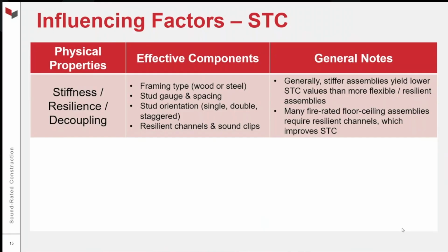So thinking about those effective components, the framing type, whether you're talking about wood or steel, is going to be a factor. Stud gauge, stud spacing, that's very, very important. Stud orientation: do you have a single stud wall, a double stud wall, a staggered stud wall? Are you using decoupling elements like resilient channels or sound clips? In the coming slides, I'm going to show you examples of most, if not all, of these different factors.